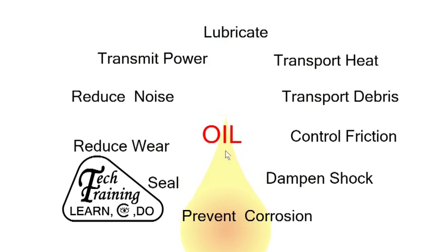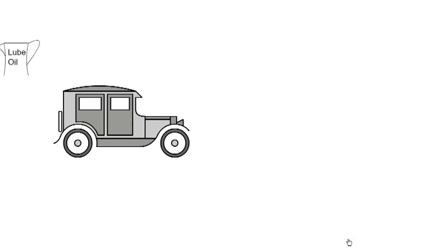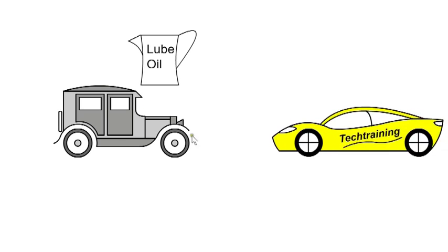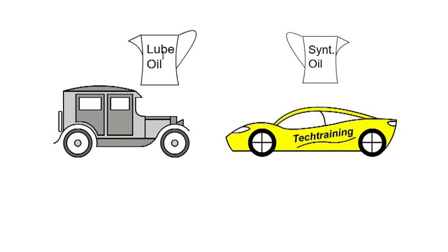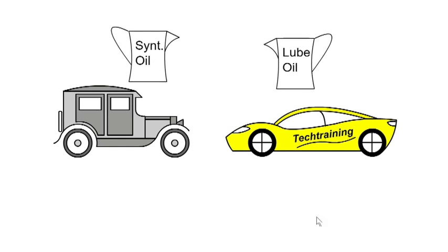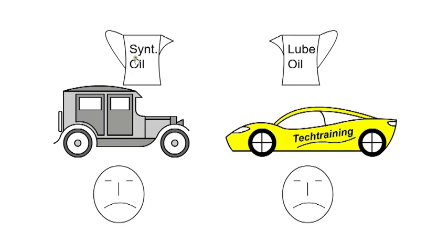Modern engines use low viscosity synthetic oil as the clearances in the bearing have been reduced and less energy is required to pump. The oil must fulfill other tasks, such as hydraulic oil for the cam timing advanced system and hydraulic tappets. The grade and viscosity must be suitable for the engine design and operating conditions. Because a vintage car has 300,000 miles and has used a certain type of oil, it does not mean that the same oil will be suitable for a modern high-efficient engine. Likewise, an expensive, fully synthetic, low-viscosity oil will not be suitable for a vintage car.